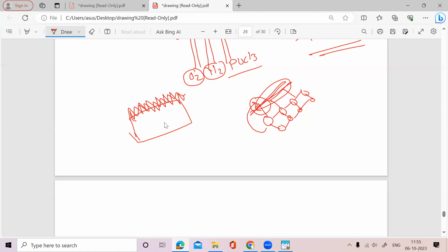Suppose you give some hydrogen plasma, at that time also hydrogen atoms will come to the dangling bonds. It will reduce some recombination. But the standard method in industry is silicon nitride. Why? Because silicon nitride does both jobs. It is treated as an anti-reflection coating as well as a passivation layer. For this reason, silicon nitride is so popular. Aluminum oxide does the same thing.